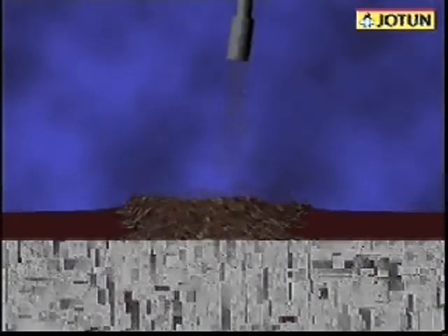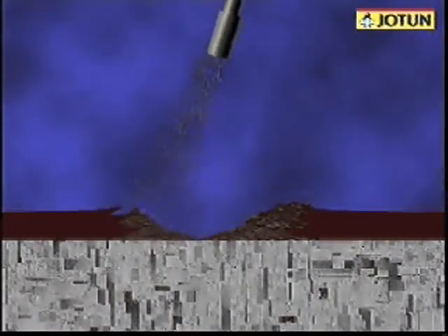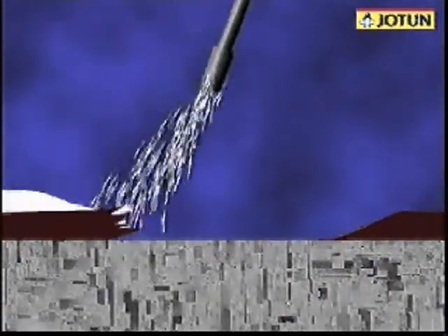Again, spot blasting removes rust but destroys the intact paint around the damage. It is important, therefore, to ensure that edges of old paint are feathered down to intact paint before applying the new paint. If this is not carried out, such areas will suffer from corrosion very quickly.